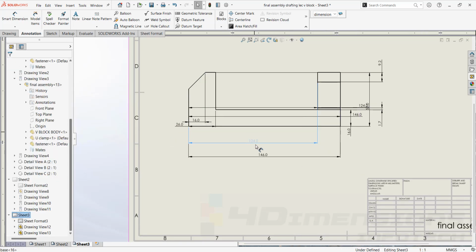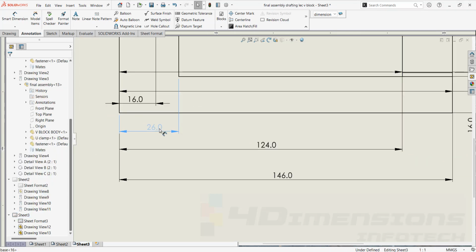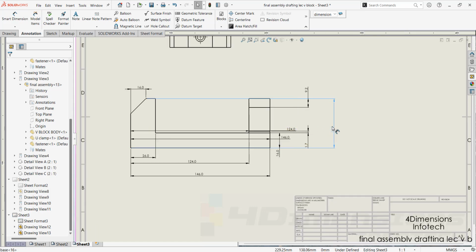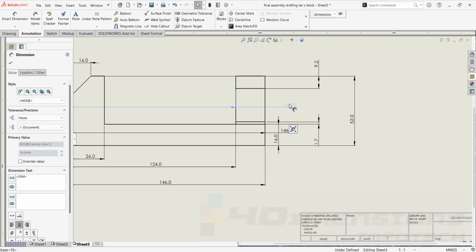here also with auto dimension, that unwanted dimensions are also given here which may not be needed much, and some required dimensions which may be important here have not been given or are not present here. That's why this auto dimension option will also not cover all the dimensions. So it is better to refer and give the dimensions manually only, as we have seen in previous lectures. So these were the options by which we can apply the smart dimension automatically, but they are not much used.